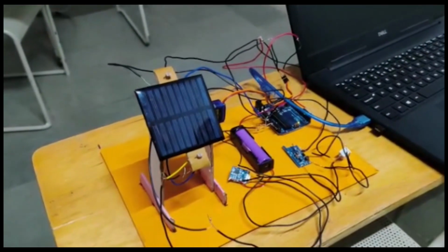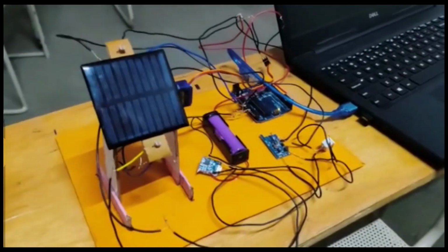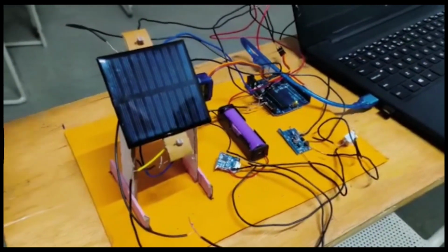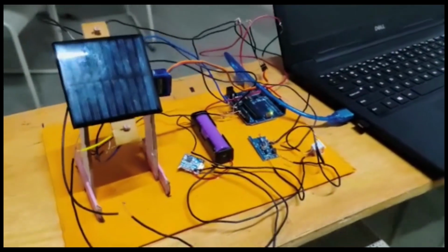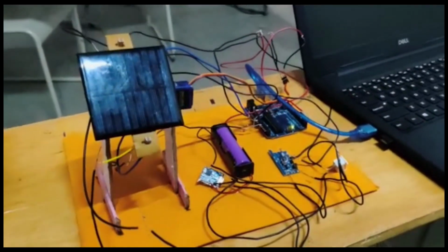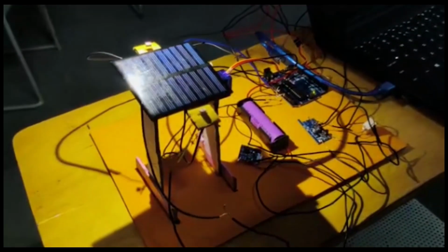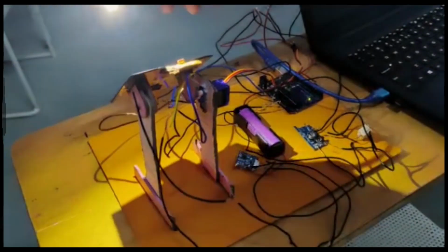Generally, in a solar power plant, panels will be in a rest position with a tilt of 20 to 40 degrees. In this project, we are going to rotate the panel according to the light intensity. We are using LDRs for sensing the light. A code was dumped into the Arduino for this operation. When maximum light intensity hits the panel, the LDR senses the light and there will be a variation in resistance.